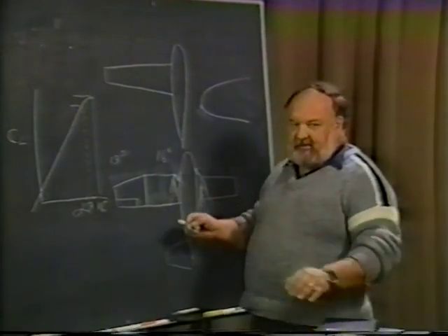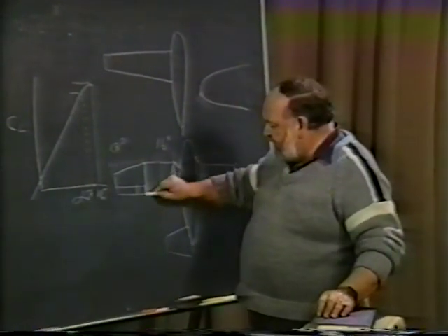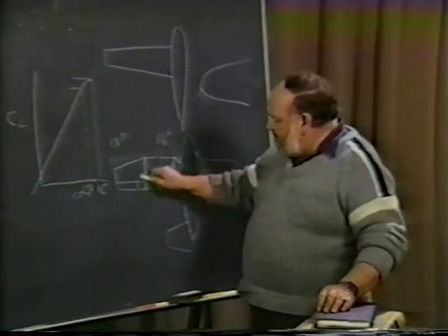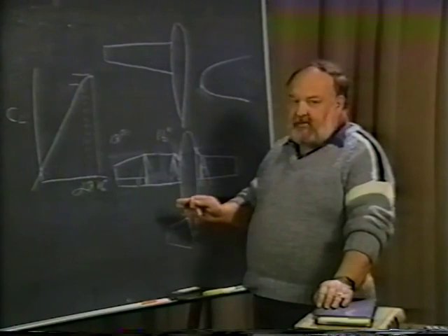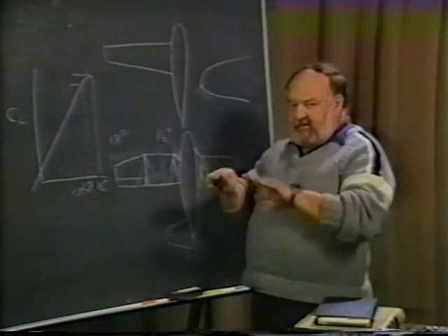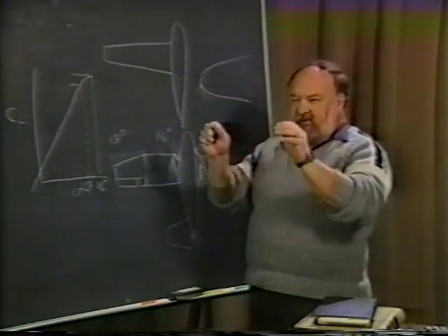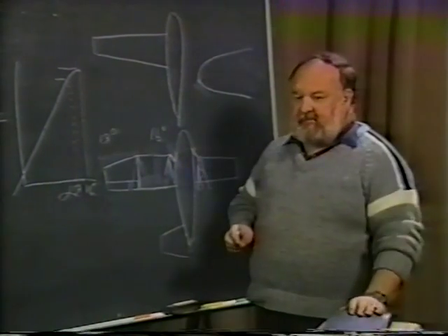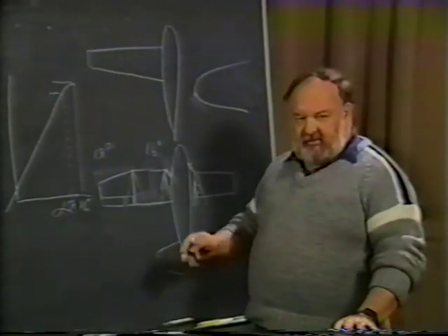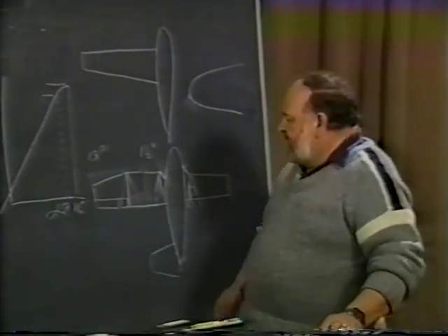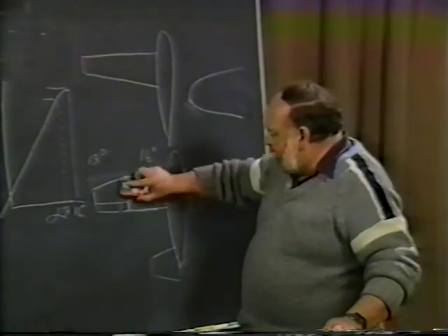It looks like a nice fancy little layout, it has good aesthetics to it, but if this break here is too far outboard, and if it's all the way out to where the ailerons themselves begin, then you're going to be causing a flow separation to begin quite a ways outboard, and it's always dangerous because it's not that easy to make an airplane fly through very smooth air and pull it up and stall it without any yaw whatsoever to it, and therefore to have both wings stall exactly at the same time is not that easy of a thing to do. And many times, with just a little bit of yaw to it, one section will stall first, and that means the airplane will start to roll. So something nice inboard is a good approach, trying to stay away from something outboard on the thing.